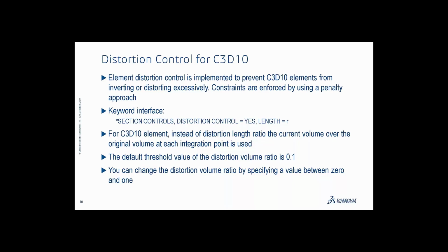So this is really intended for those simulations with extreme deformation, where elements can potentially flatten out or even invert. Obviously, when an element inverts, then that's it. The simulation's done, gets kicked off the machine or something like that. Floating point errors, etc. When you really want it to keep going. You're not interested in the results at that specific element, obviously, but we want to keep the simulation running.